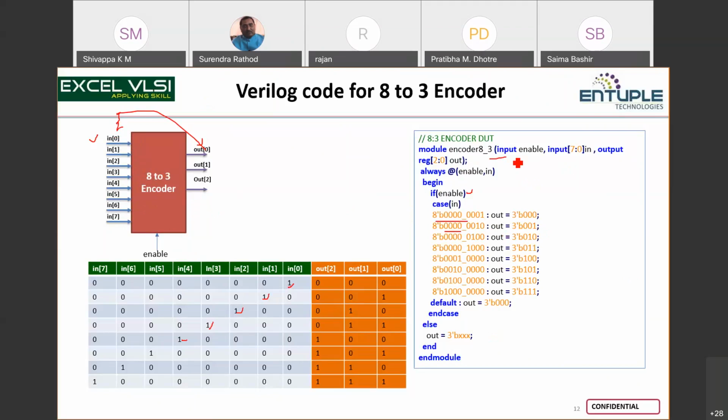Hope you're following the way the codes are written. Here enable, input 7 down to 0, 8 inputs, 3 outputs, and sensitivity list enable and in. In actually is 8 bits, so all are included. Whenever any change happens here, if you observe in all of these circuits I am talking about, you don't see clock, you don't see reset. Those are part of sequential circuits.